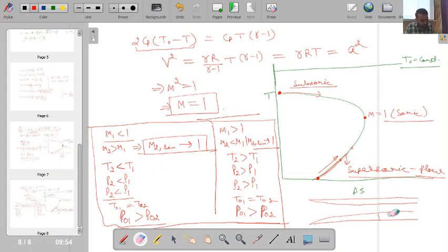Okay, so ultimately you can see that in this particular zone which is at the core, I can consider this boundary layer region almost a stagnant situation where fluid is almost stationary, and in this central region I will be having the high velocity. So as area along the x direction is decreasing, our flow velocity and the Mach number will increase. Okay, so for subsonic flow situation. Now I will once again come back to this point, M naught equal to 1.